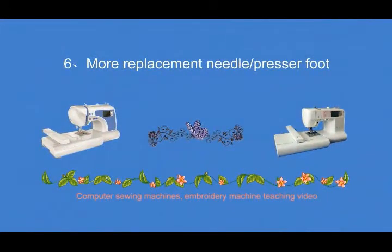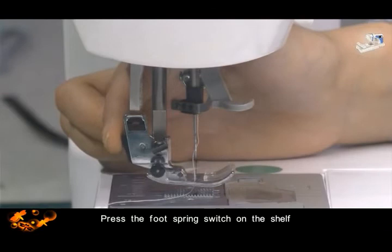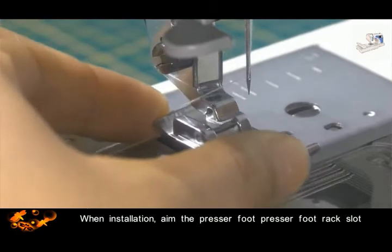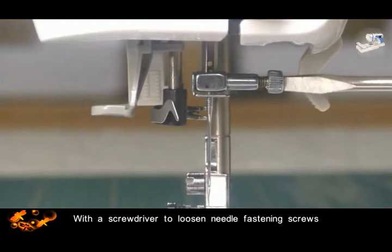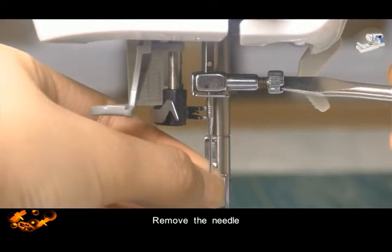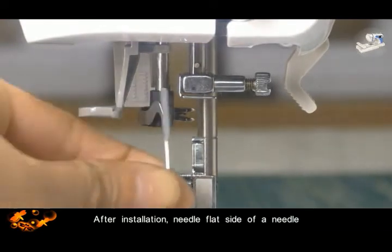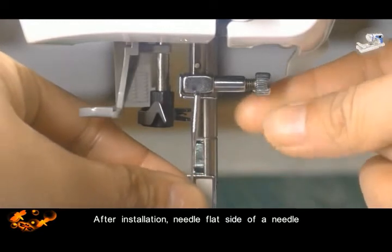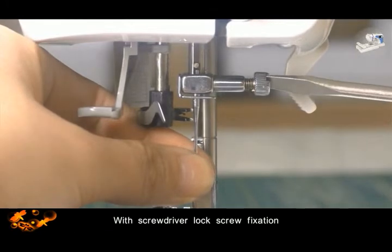Six. Replacing the needle / presser foot. Shut off the power. Press the foot spring switch on the shelf. This sets the presser foot to a free state. When installing, aim at the presser foot rack slot. Put down the presser foot lever, and use a screwdriver to loosen the needle fastening screws. Remove the needle. After installation, mind the flat side of the needle. Lock the screw with a screwdriver to fix it.